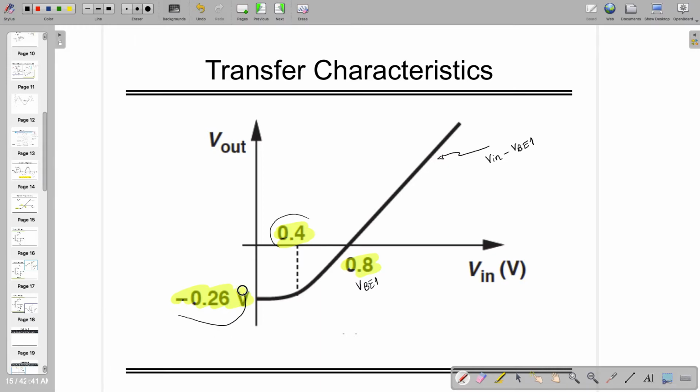and these numbers came from the fact that the value is given to us, and this one is also from that. So these numbers actually change with respect to what current you are feeding, what value of resistance you have, and what device characteristic you have. However these numbers change, the output will go below the zero line and follow such a characteristic. Or you can say that Vin versus Vout will look like this one.